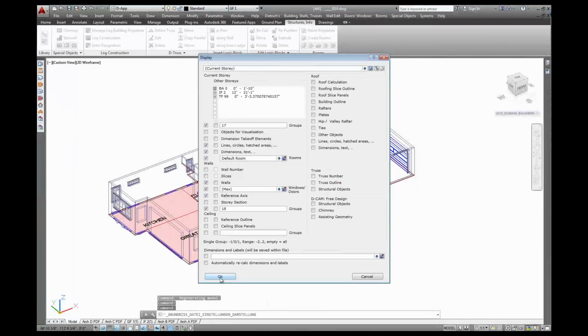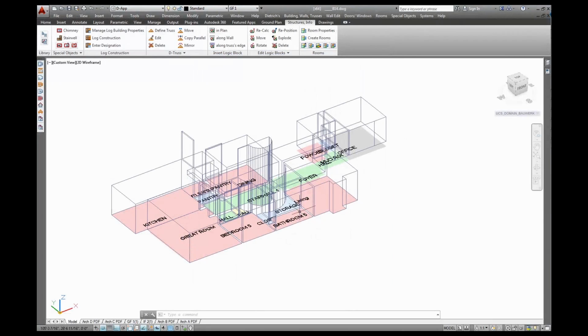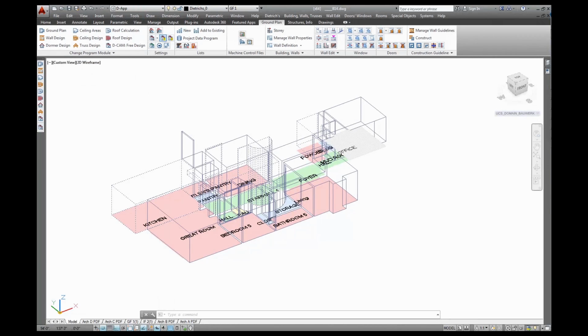But there's also a 3-dimensional side to it that gives me the air volume of each individual room, and together with the air volume, the energy that's heated, that's stored inside that volume. So that's the blocks that represent the volume of each room. There's the staircase winding up, so that goes up to second floor level. Over here, garage, office, all individual volumes, so I know exactly how many cubic foot of air have to be heated.